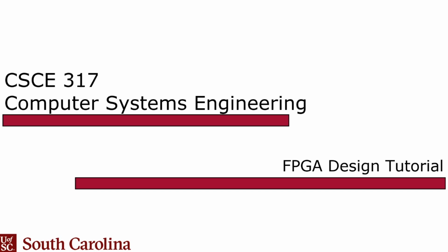There are other Arduino chips, but that's the de facto one, the original one. There's a reset pin, and on the Arduino board that reset pin has a capacitor to ground, which is typical for reset. So you hit the reset button, it charges the capacitor, and it basically sends a reset signal to the device, and then the capacitor discharges. So it gives it a few Mississippis to be in that reset while the capacitor discharges, basically.